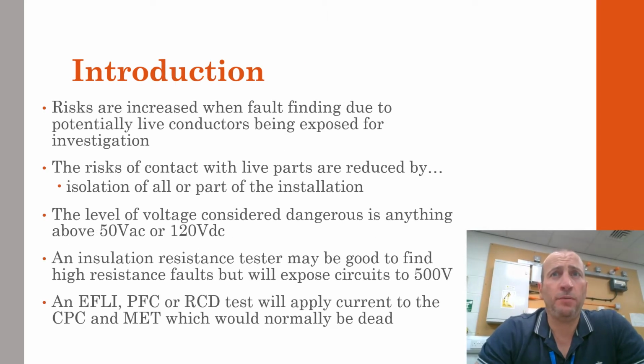Risks of injury from electric shock are increased when fault finding. This is due to live conductors potentially being exposed during the investigation process. Other risks that exist when fault finding include damage to tools, equipment and property. In order to reduce the risks associated with fault finding, electricians follow the safe isolation procedure to remove power from all or part of an installation.